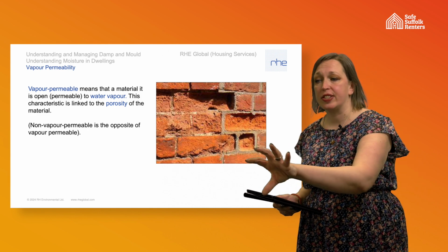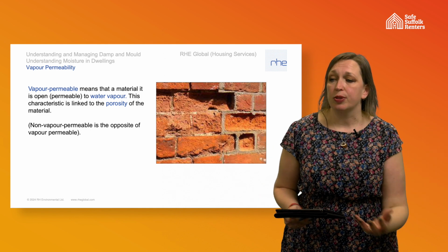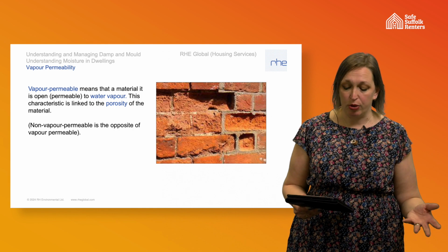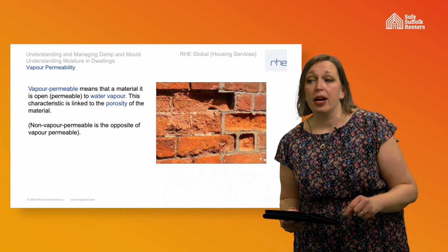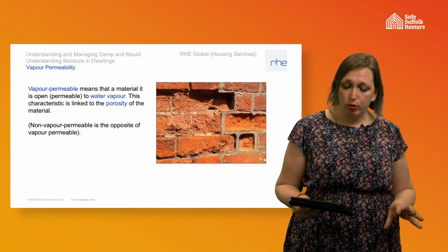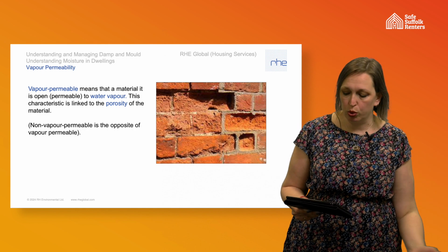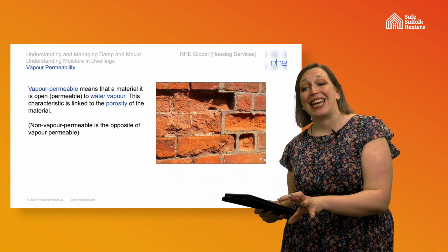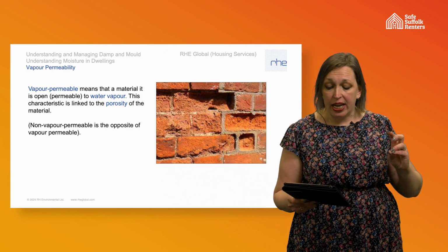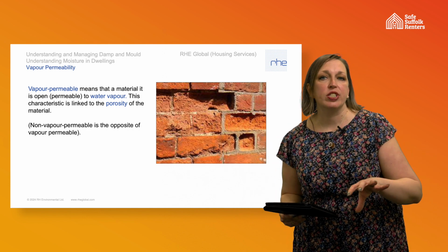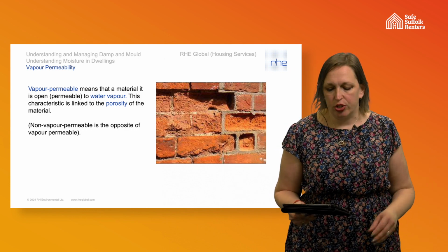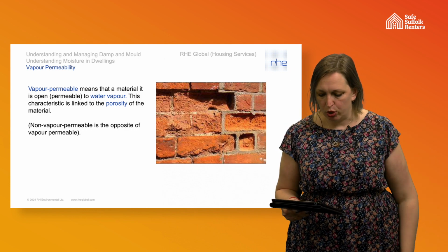So in this picture, the moisture hasn't been able to move through the cement mortar, so it's gone through the bricks, so it's damaged the brickwork. On top of that, cement mortar doesn't really bond well to lime mortar, so that can also trap moisture within the bricks, leading to frost damage. So in this particular case, what we saw was that all the repointing that had been done in cement needed to be scraped out, and that needed to be repointed with lime mortar to maintain that moisture route.